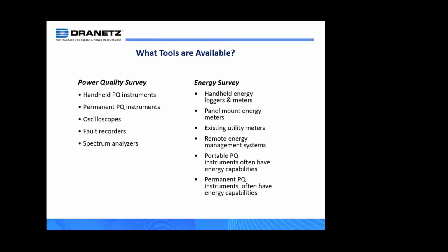Some of today's technologies where PQ handheld instruments can also be used as sort of semi-permanent or even permanent instruments, because they have things such as communications like Ethernet or wireless communications. They have sufficient memory which can log data for long periods of time. So, out of this category here, handheld PQ instruments, or power instruments, I should say, it's probably the most versatile.